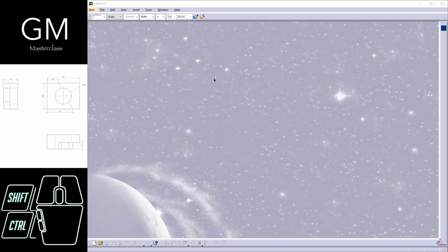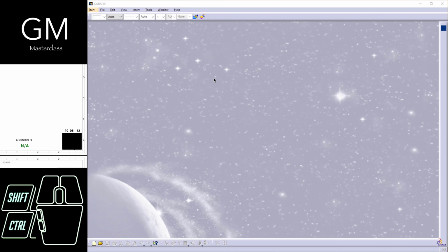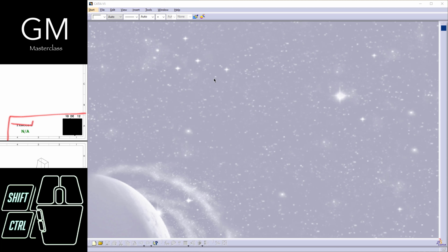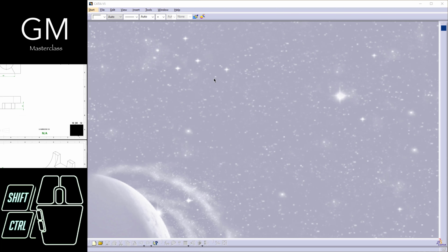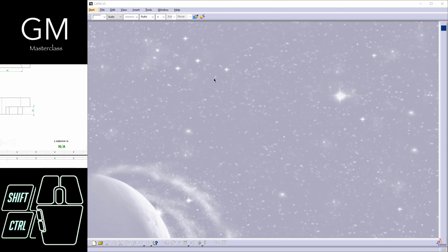The second thing that I have to take into account is the unit system that the dimensions are using. In this case, I cannot find any information next to the dimension, then I'm gonna look around within the engineering drawing. There is usually a box right here that contains not only the unit system but also the material, the name of the part, the person who did this engineering drawing, the person who checked it. But since I cannot find information about anything right here, I can assume, and this is a rule, that these are millimeters, right?